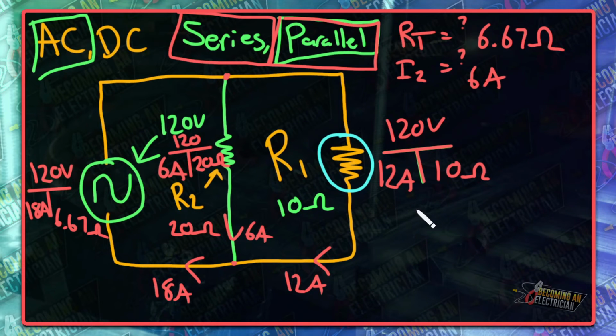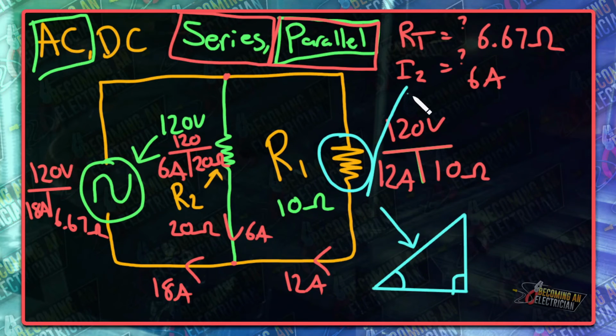But once we start going more technical with things like inductors or capacitance, we are going to be looking at triangles and the Pythagorean theorem. And it's amazing how much we do this stuff. All you're trying to figure out is the hypotenuse, and you're trying to find the angle for the power factor. But in a basic circuit, we just follow what's called Ohm's law. And that is V, which could be E, but again, keep it simple. V for voltage, I, but if it was A, it's easier for amps, because as real electricians, we talk about volts, we talk about amps, we talk about resistance, okay?